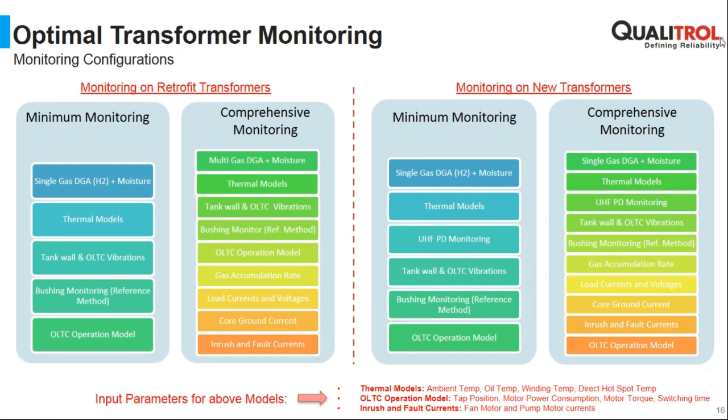If you're talking about higher voltage and the use of capacitive control capacitor bushings, then yes, the transients are basically not so good for the bushings usually. Over time it can create a kind of partial breakdown between the layers, and that can be detected by bushing monitoring.